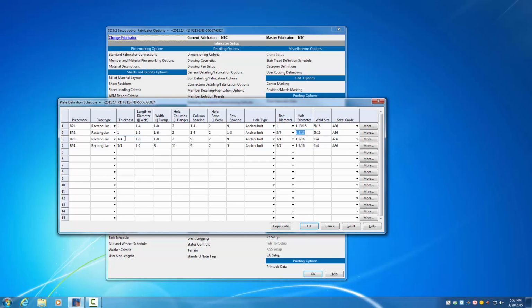And as I'm going through these, I am writing them numbers, BP1, BP2, BP3 on my anchor bolt plan. That way when I go through and input my columns, it's going to ask me for the base plate, and what I look for is the BP1, BP2, BP3. But when SDS2 actually picks the base plate out of the schedule, when we get into the model I'll show